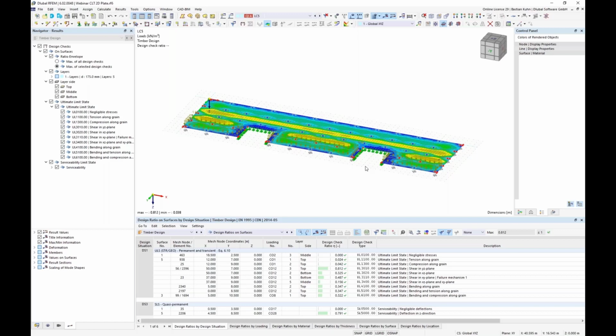You can compare it with a continuous beam. If you have 2 fields, you also have to introduce the live load on the left side and on the right side, because for the middle support, the highest force will be with live load on the left side plus live load on the right side, but the highest field moment is with the load only on the left side, if it is the longer span, for example. Okay, so I hope that's clear.